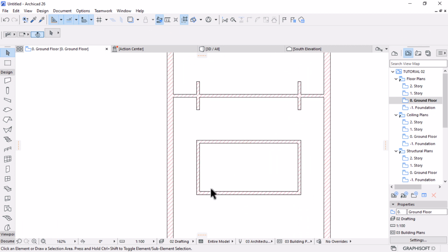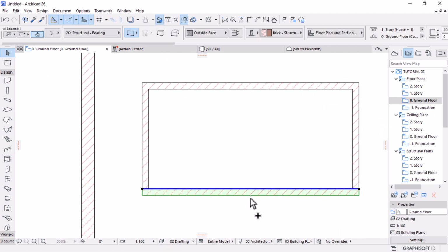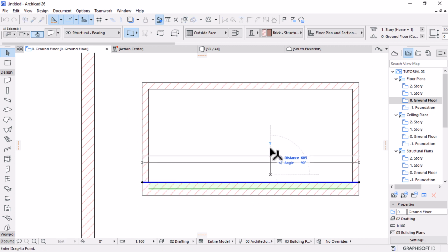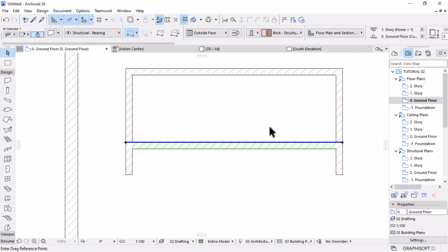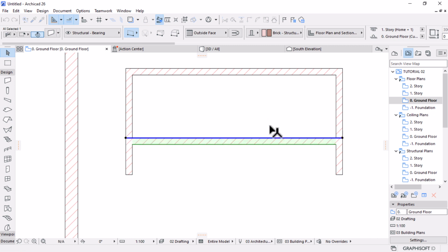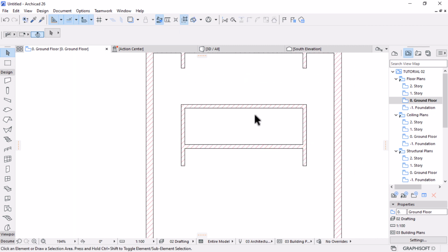Okay, and then from here what I need to do is take this wall, Control Shift D to make a copy, put it aside next to this one, and then move it around 600, which is going to create a cabinet or cabinetry for the kitchen. And then I can get rid of this wall, right? I can make this, instead of 600, make it 700. I'll add 100 on top, something like this for the kitchen.